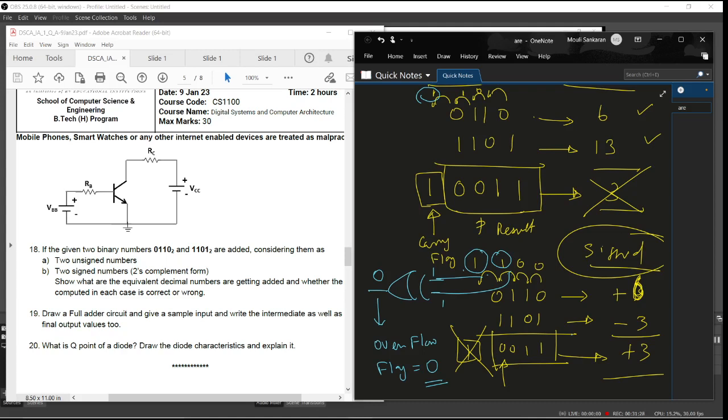So what happens in real hardware is we will look at either this flag or the carry flag I told you about earlier. One of these two flags will be looked at to find out whether the result we have computed is correct or wrong. The hardware does not know whether it is performing unsigned or signed arithmetic, because it produces the same results in both cases. Only thing is, in the unsigned case, only the carry flag was looked at, whereas these two carries, which result in the overflow flag, are not looked at. In the signed case, the overflow flag is going to be looked at.